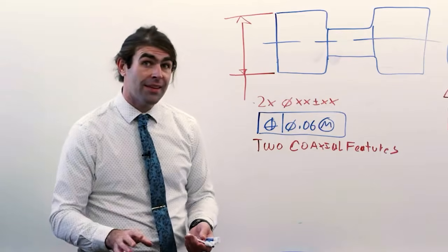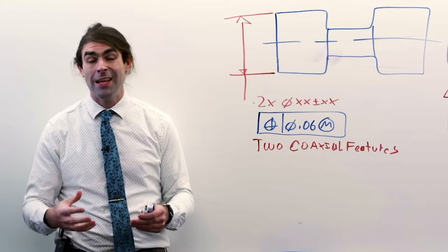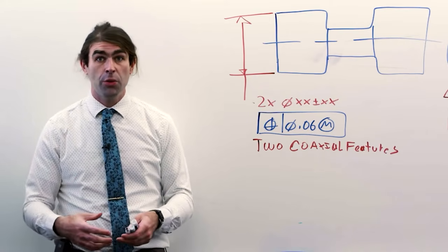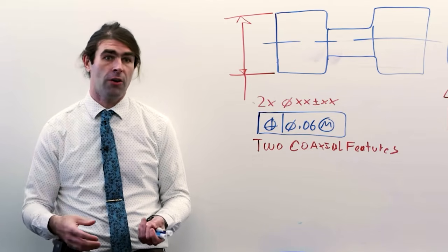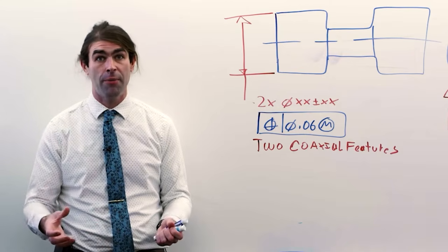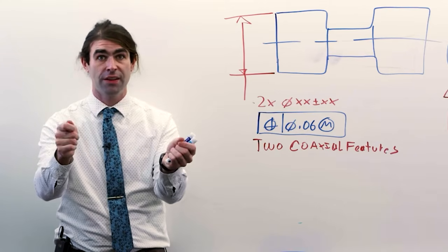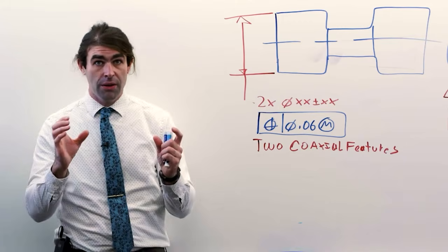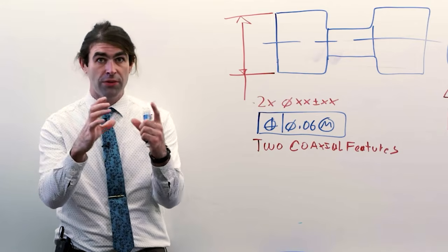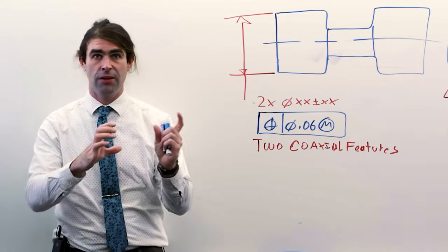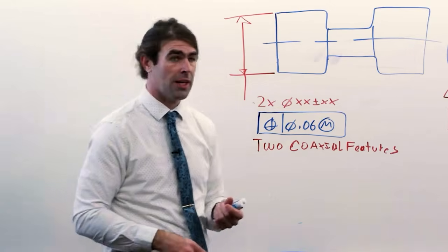Okay. So the last thing we have to talk about in this video is a repetitive pattern, repeated datum reference frame. So this is a common thing in something like an instrument panel. So say you've got, not for a modern car, but like an old-timey race car, you're putting a speedometer in, you've got the bezel, and then you usually have 2 studs or something that's going to fit through 2 holes. Well, that pattern, that feature, is going to be related to the center bezel and the outside, but not any other instruments on the panel. And we can reflect this with GD&T. Let me show you what I mean.